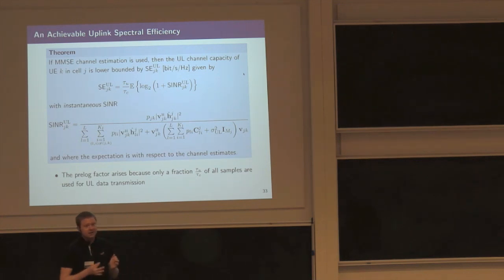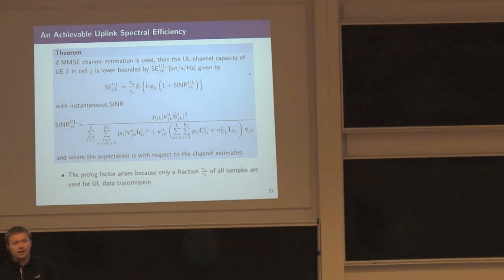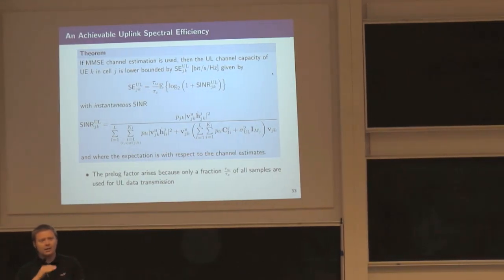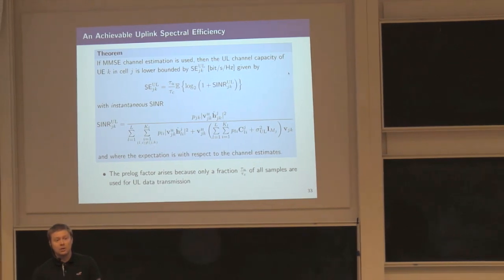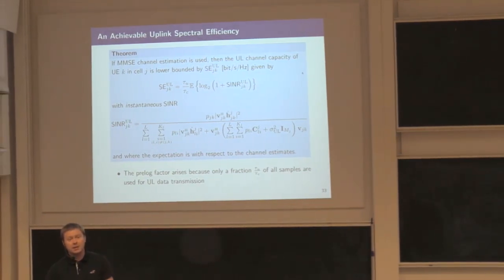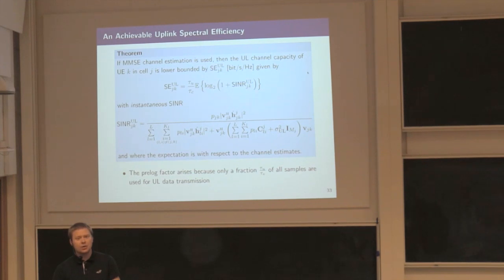Then the follow-up question is, do we get channel hardening with a correlated channel? Yes, usually you get that, but it might harden more slowly, because it is really the number of eigenvalues that you have that are strong and are at around the same value that provides you with the channel hardening effect. So in the examples that I had, when you have 20 strong eigenvalues, the hardening will be as if you had an IID Rayleigh fading case with 20 antennas. So you might need many more antennas to really get a good hardening effect.